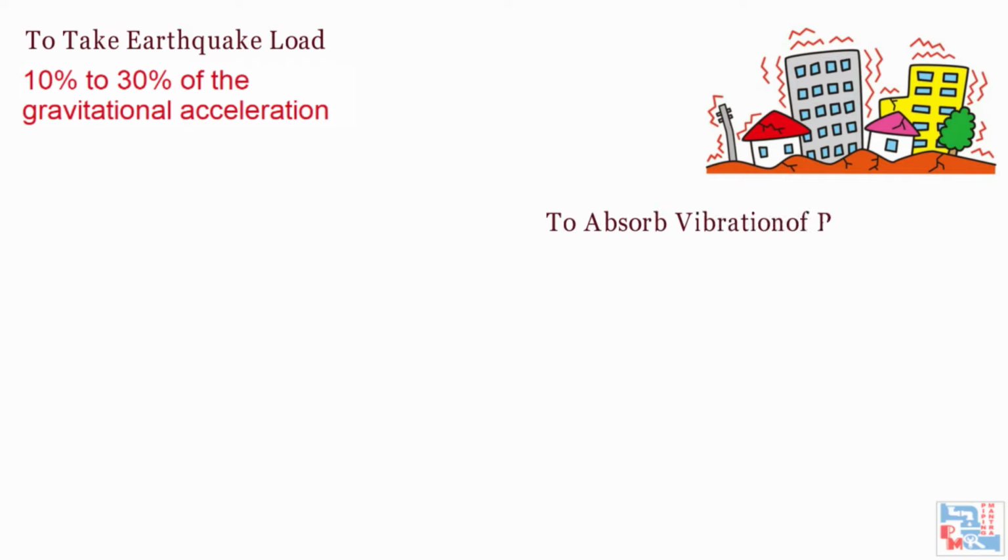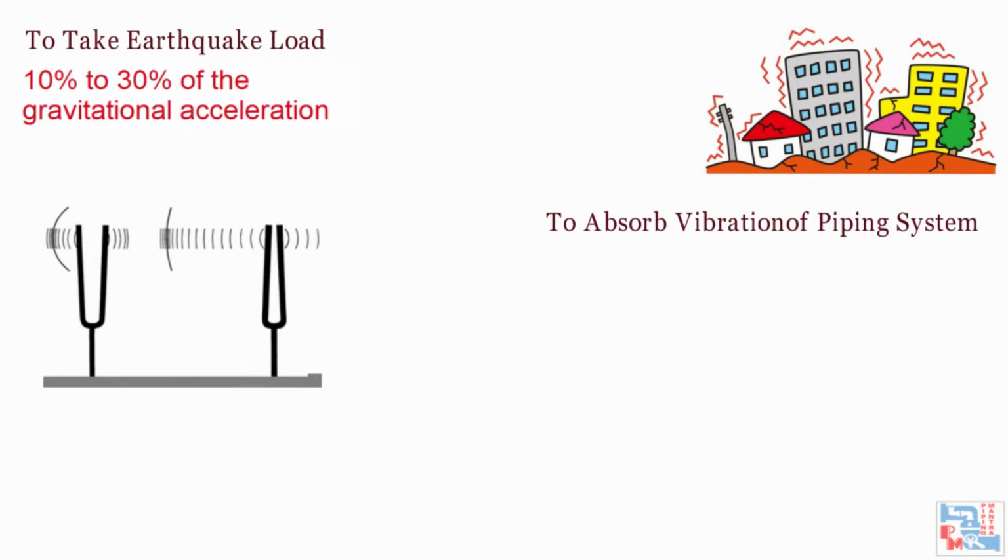Next is to absorb vibration of piping systems. When the pipe is subjected to moving machinery or pulsating flow or very high velocity flow, pipe may start vibrating vigorously and ultimately may fail, particularly if span is large.